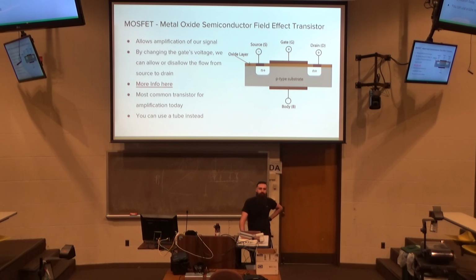Would there be different kinds of transistors specifically for audio purposes? Yes, and they developed them specifically to work in this paradigm, such that when they heat up, we want them to be less susceptible to temperature change, like we looked at earlier with the resistors. Same thing happens, except with the resistance inside of this. So it's not actually able to amplify the current at the same points. That's a good thing you brought up, because this happens naturally as well. These will be non-linear, and that's how you get problems with your amplifier.